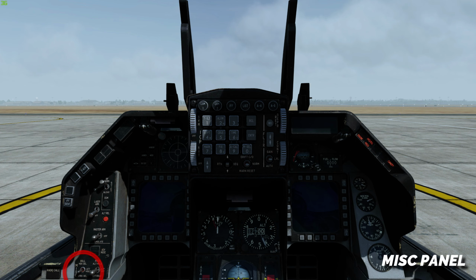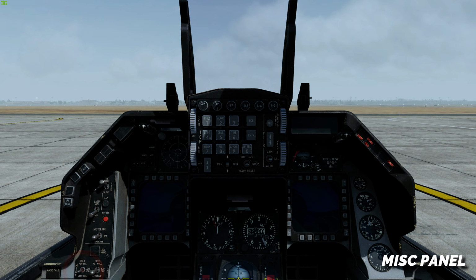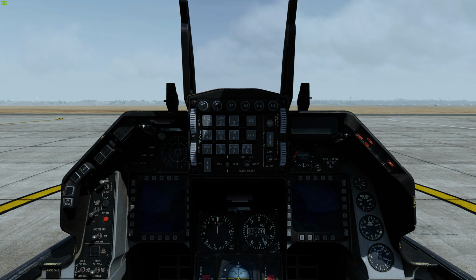Roll is in the attitude hold position. When in the attitude hold position, the autopilot maintains current roll attitude by INS. In the steering select position, the autopilot directs the aircraft to the active steer point. Note that the roll switch is functional only when pitch is engaged in altitude hold or attitude hold.